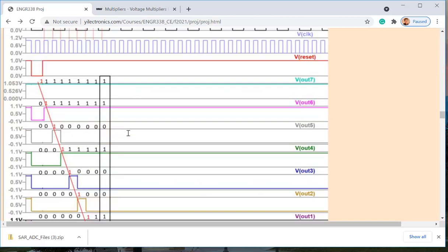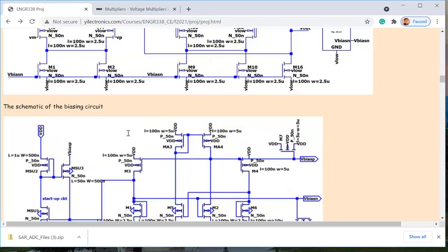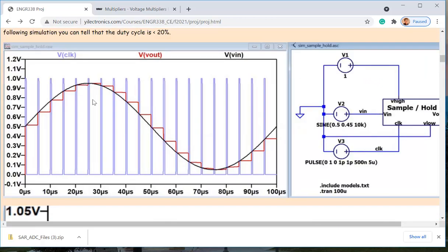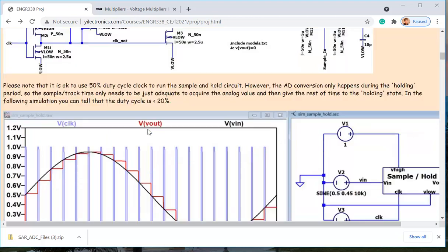So that's why the clock looks like this, because the original clock is always oscillating in between, but only gives you a rising edge after it comes to 10. Okay, that's the clock you should use for the sample and hold circuit.